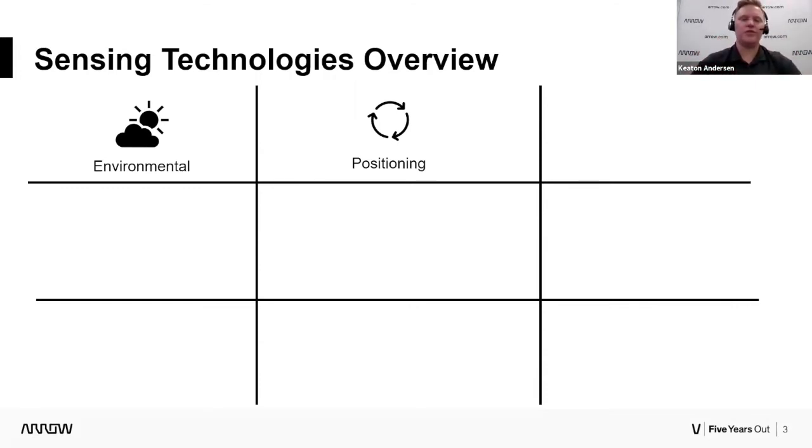A great example of this is your phone, right? When you go to pick up your phone, it has an accelerometer built into it that says, hey, I've been moved, wake up, determine that there's something there. Accelerometers and gyroscopes, as well as inertial measurement units or IMUs, have become increasingly common in all sorts of devices, right? You're going to need accelerometers in particular for sleep power. You can turn a device off and let it sit, and until I detect that movement, I'm just going to stay in that sleep mode. And that prolongs battery life.